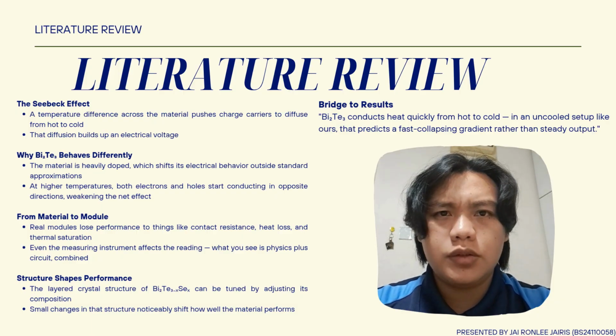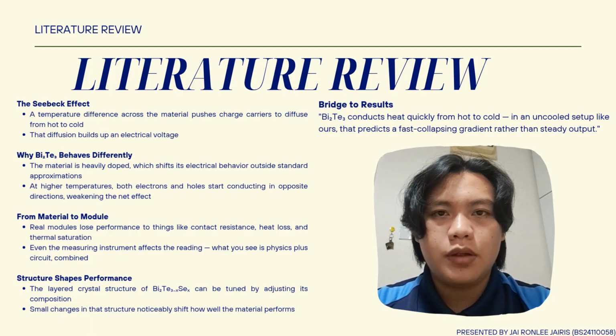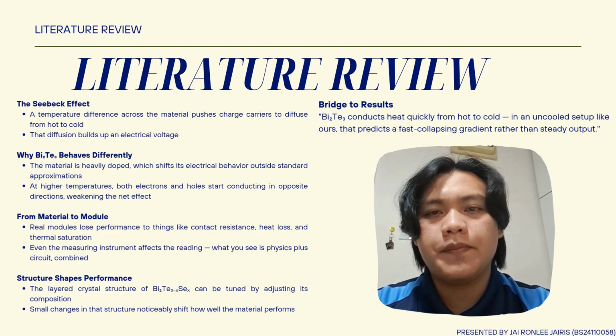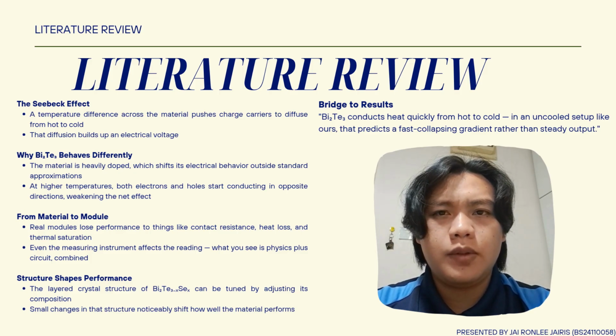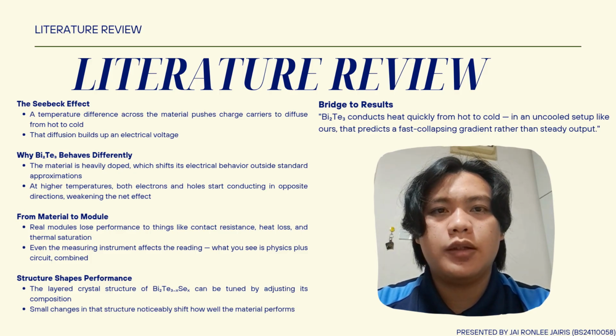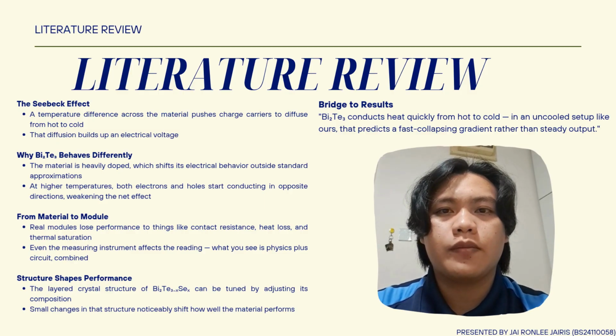But lab conditions do not equal reality. In our actual setup, we lost performance to wiring resistance, heat escaping, and the cold side warming up. Even the multimeter used to take our readings adds its own small load to the circuit, meaning what we measured was never purely the material's behavior alone.